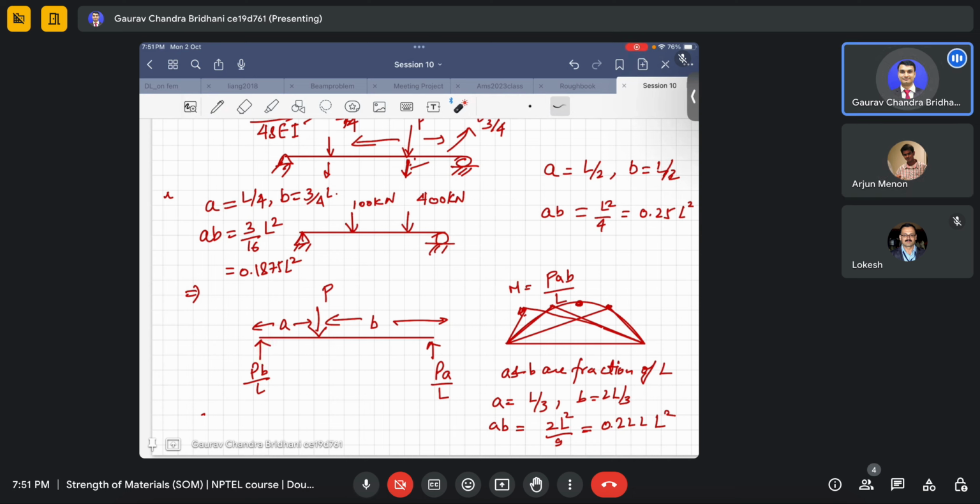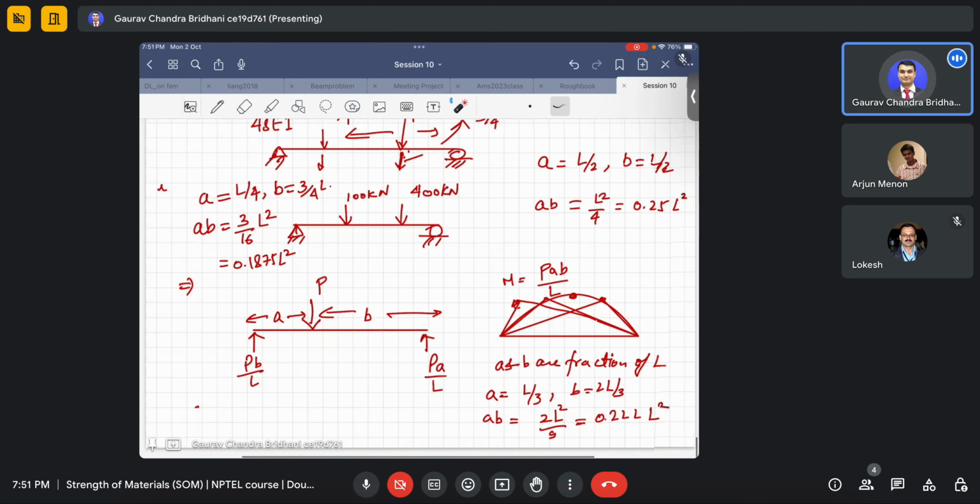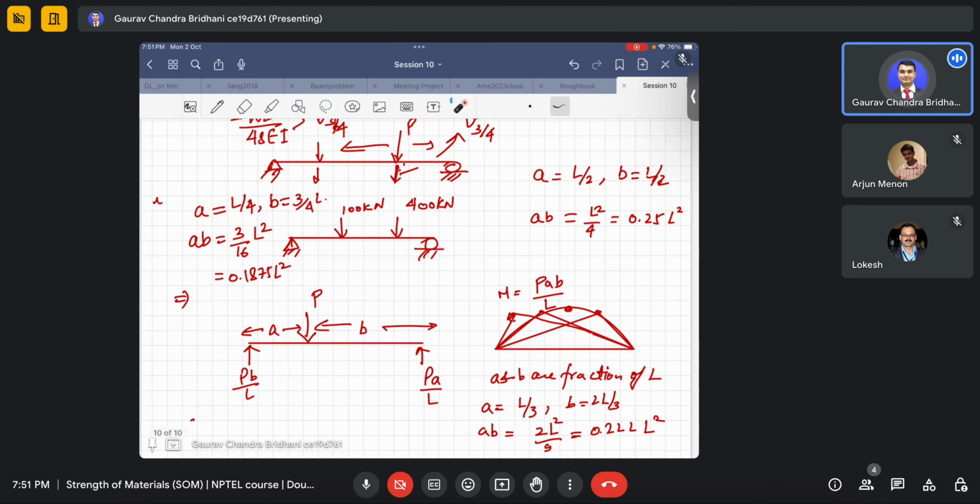Just imagine you put two bricks some distance apart, and then put a wooden plank on it, and first start standing at the center. You stand at the center, you will see that both sides are bulging, or bending, in the same way. Now as you move towards either support, it will bend more and have more depression. Exactly as you said correctly, there will be more slope here.